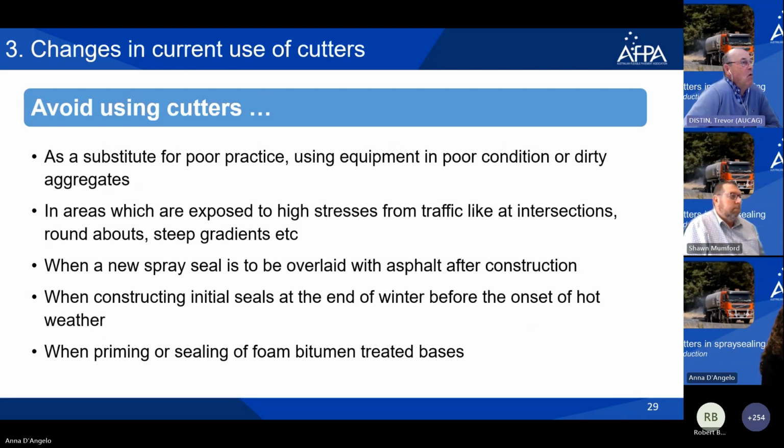What's also been said before, using cutters is seen by a lot of parties as a panacea to covering up poor practices, and especially spray equipment that's not in good condition, or even aggregates that we receive from the quarries that are not clean and dry and are sometimes dirty. So we need to look carefully at how we deliver these spray seals, so that we avoid having to compensate by using cutter in the construction process.